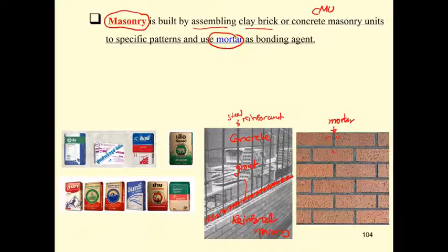The crushed stone and sand used to have very good gradation, and the proportion may be 1 cement to 2 sand to 4 crushed stone by volume. And then we have the word mortar. The mortar is used to bond the bricks together, or it is also used to pave the surface of the brick. Mortar usually is the cement plus sand.